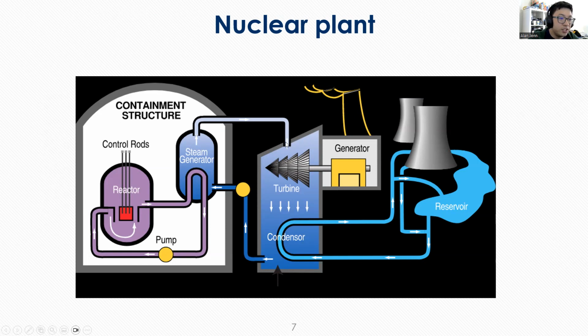And then to cool down that steam, you have a condenser with a separate water loop, right? And again, as a reminder, the reason why we do this is that you can't really have dirty water going through the turbine. That would increase the amount of maintenance that you would need to do. You can contaminate the turbine with materials in the water. So generally, you want that loop to be as clean as possible.